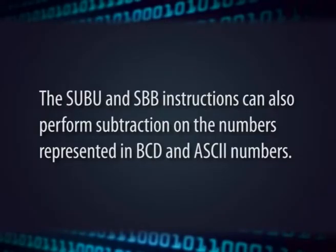In the earlier topic, the addition of BCD and ASCII numbers was explained using the DAA and AAA instructions. The SUB and SBB instructions can also perform subtraction on numbers represented in these formats. However, to bring the result into BCD and ASCII format, an adjustment of the result is needed.